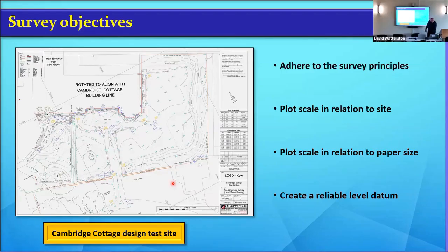So if you know that that would fit nicely on an A1 size sheet, you could say to the survey company, I'd like it on 100 scale on an A1 size sheet, cheers. And I would like the building orientated, the face of the building orientated to 270, so it's twisted. So then it should come back with the north point twisted because the sheet's been twisted round, and it will fit nicely.